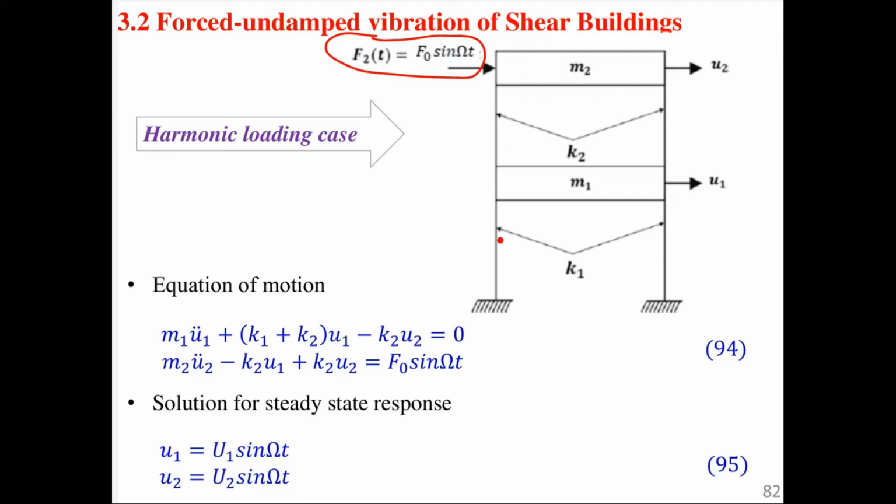Not that they don't have mass, but we assume the mass of the slab and the beam is quite large, so we can ignore it compared to that of the column. We can safely ignore. Again, remember, for dynamic loading, we are only assuming the deformation occurred due to laterally applied load. So we ignore, even though, look at this, for example, the mass here, we are saying the mass is concentrated